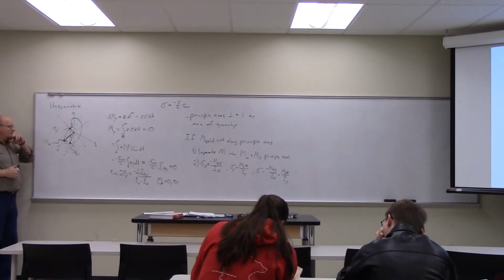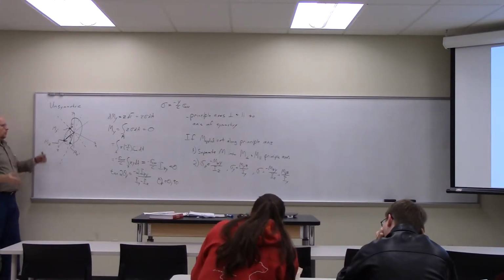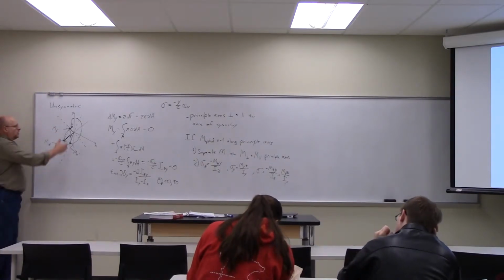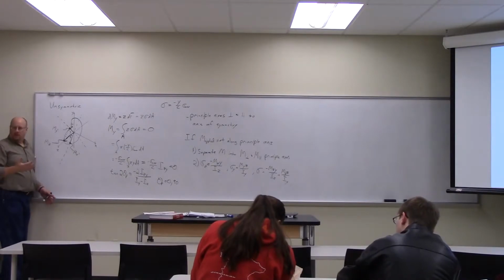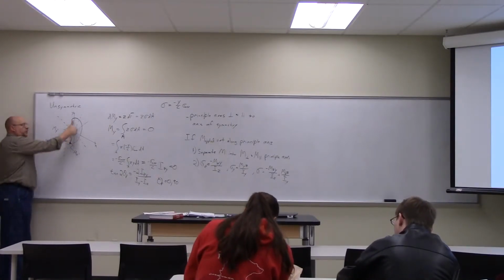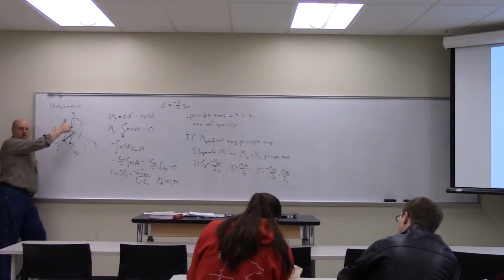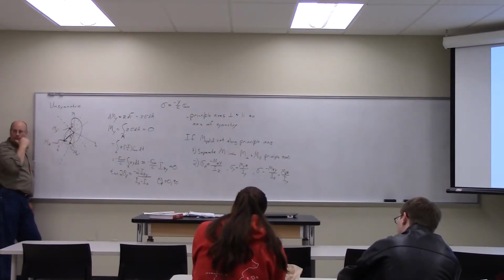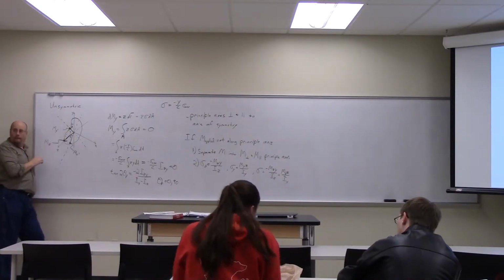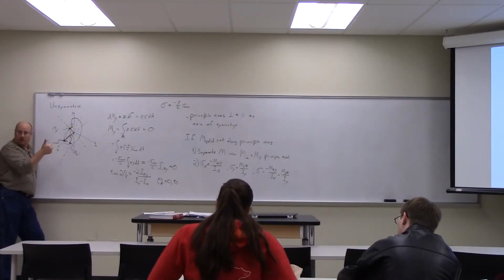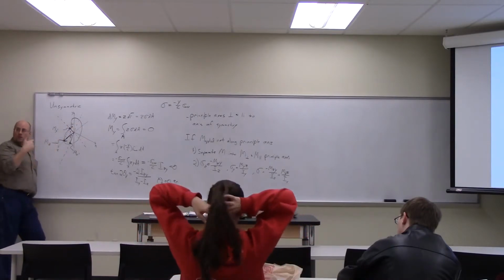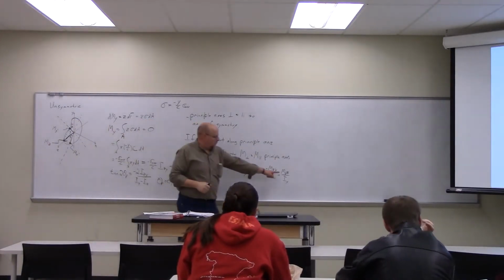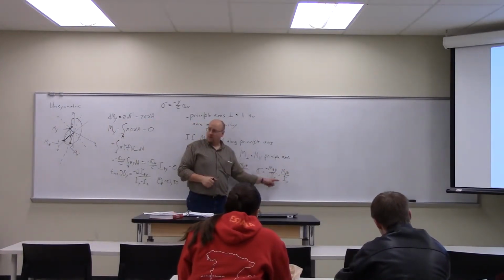Just look at it in terms of the non-primes because they're a little clearer to see on the board. Anything that's going to cause a positive moment in the y-axis is going to involve a compressive force on the z side. But it's a negative z. So I have a negative force, because it's compressive, and a negative z, and those two combine to make a positive moment in the y. So that term is positive.